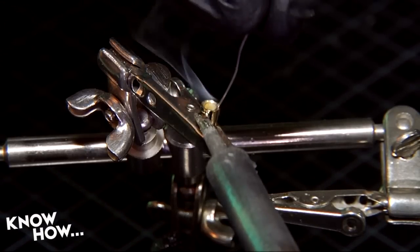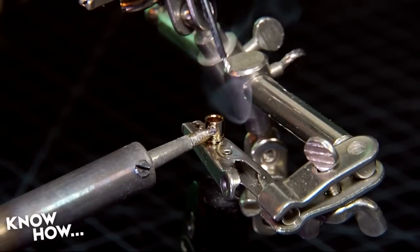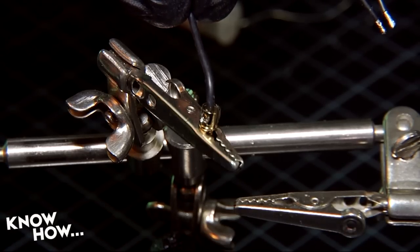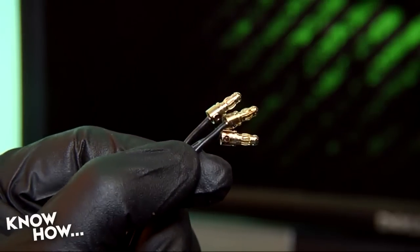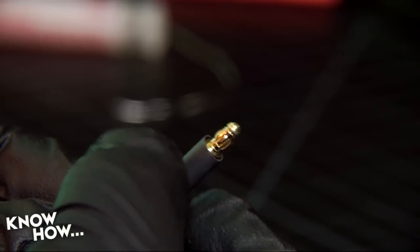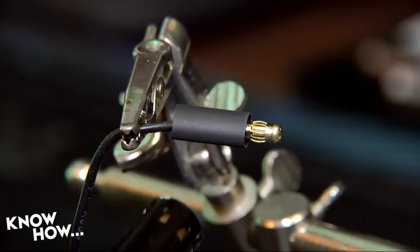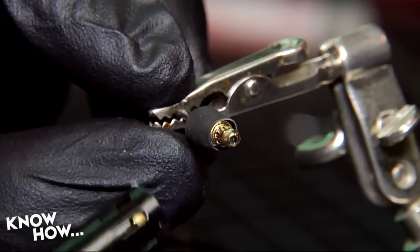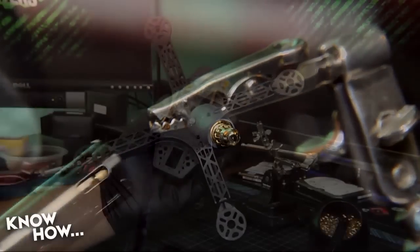Solder male connectors onto the ends of each of the motor's 3 wires by filling the mounting cups halfway with solder, inserting the lead, reflowing the solder on the wire, and allowing it to cool. Check the solder joints to make sure that you have a solid connection to the bullet. Repeat for all 12 leads, then insulate each bullet with a 1/2 inch piece of 3/16" heat shrink tubing that covers everything from the base of the bullet back.